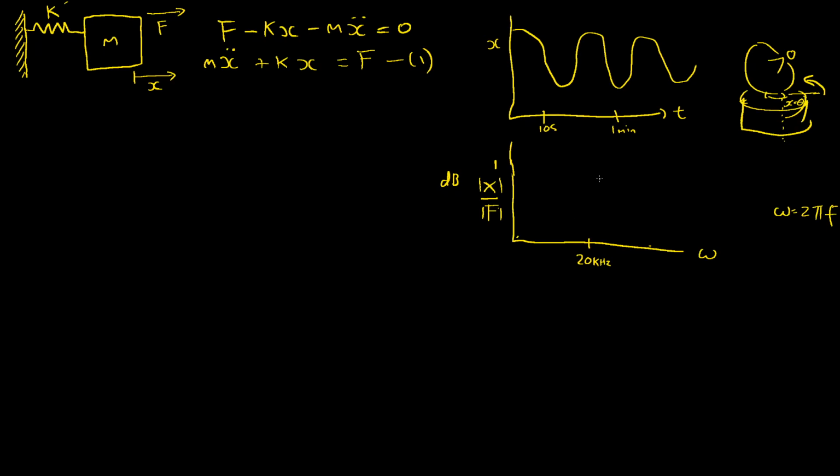And what you'll find is going forward, you'll probably work in the frequency domain much more than you will in the time domain. A signal that looks horribly messy in the time domain can usually be very simple in the frequency domain. For example, if this was rotating at a constant rate and was just a sine wave with a frequency of 2 hertz, in the frequency domain at 2 hertz, you would just have a peak.